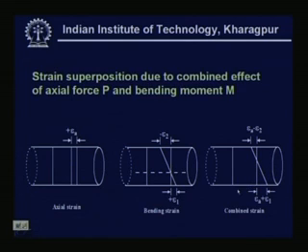Now, in design we know that mostly all our stresses will be very much within the yield stress limit, thereby the amount of strain will be very small. So, it is possible that this superposition theory holds good. That means it is possible to superpose all these types of stresses.